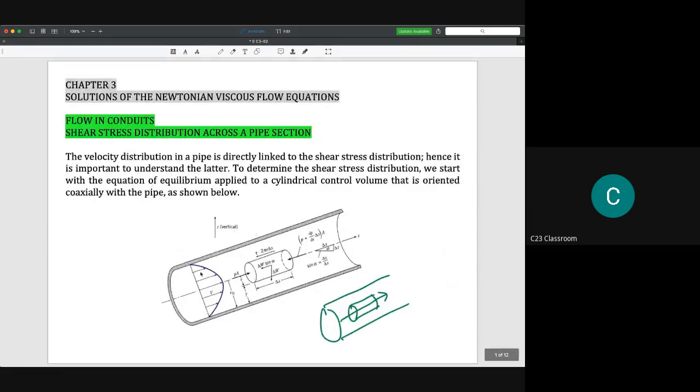Okay, let's say we have the cross-section of a pipe here. As we know, because we are discussing a fluid with viscosity, the no-slip condition will occur at this wall. Please note that this is a circular pipe, so the contact between the molecules and the pipe surface creates a very hard contact, so the velocity of water is equal to 0.